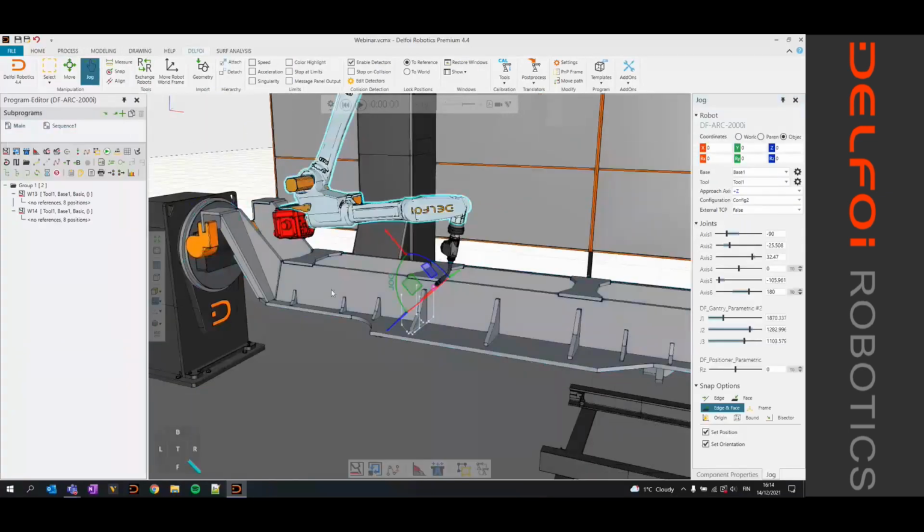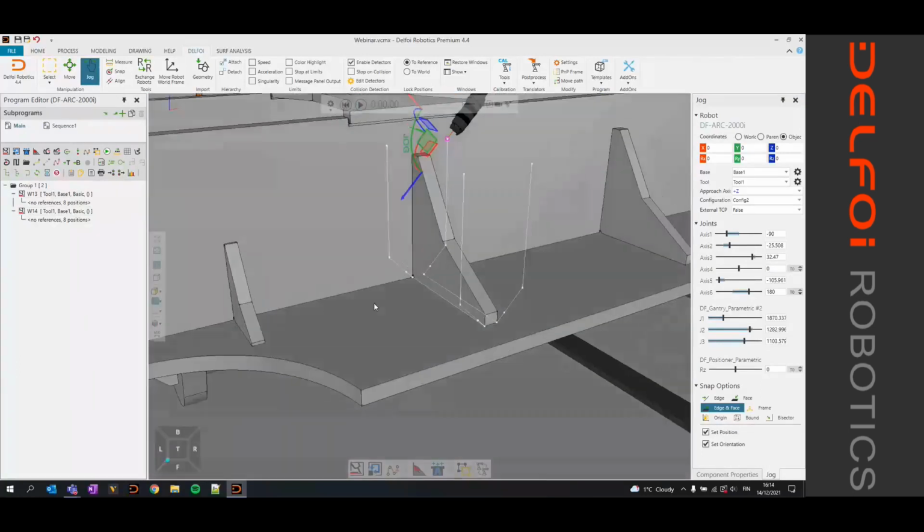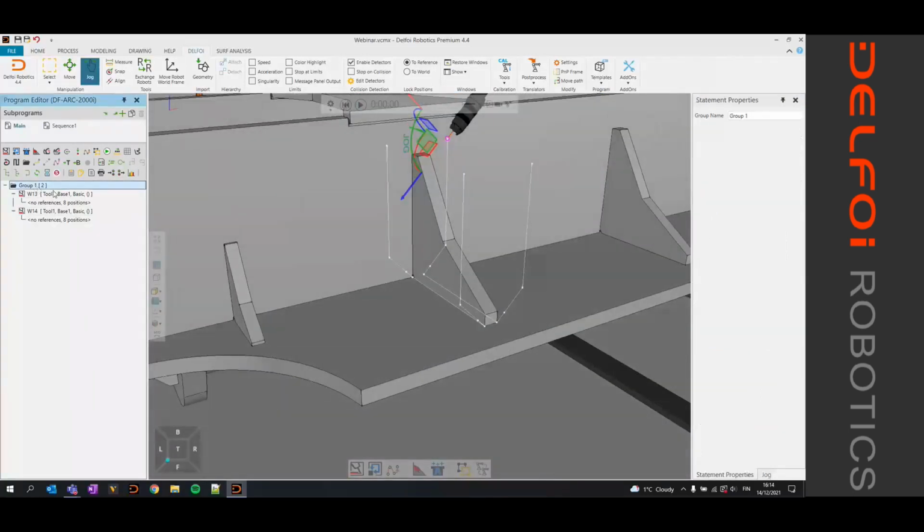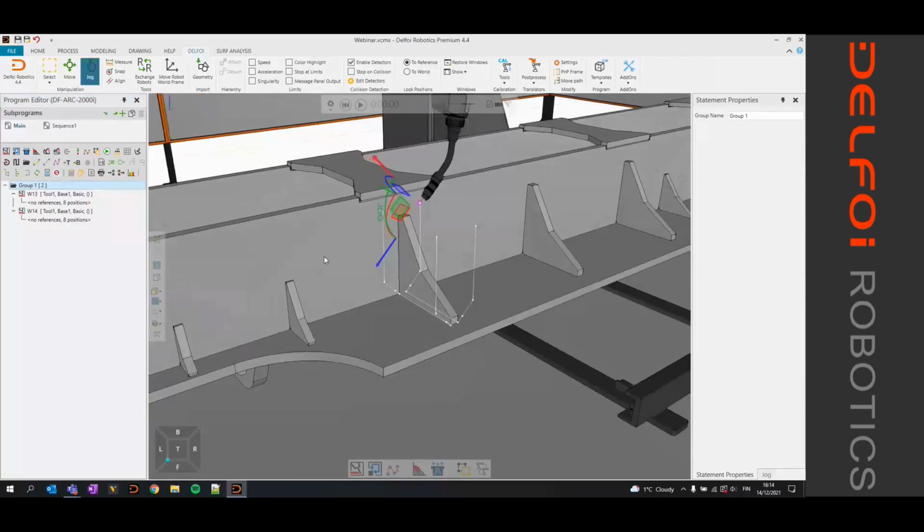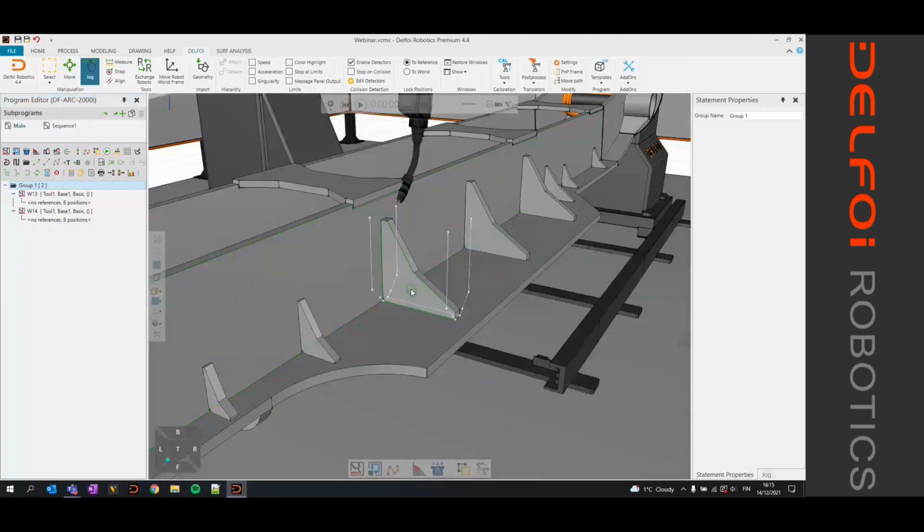So in these cases, we can use the group statement to take these wells that we have generated for this first group and use that to either move that group or copy and clone the group to another position in that workpiece. So one mouse right click allows us to set an origin to this group, which will then ask you for normal surfaces where it will place the initial location of the origin for the group.